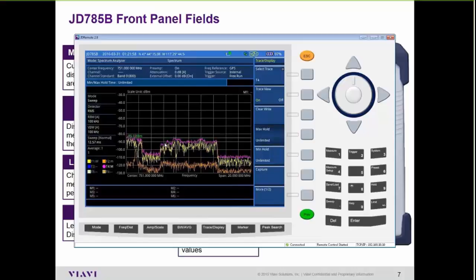And so you can see the variance of power across here. At times we're seeing power levels that jump up to about negative 90. At other times we're down around negative 120. So there's about a 30 dB delta between the noise floor here on the downlink and the max power that's been seen at any one point of time. As we move through frequency versus time versus power, you can see the variance here of those two signals.